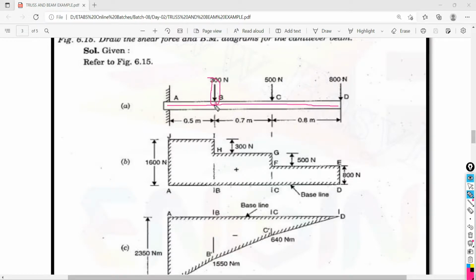That's why we took this beam like this, then took one other beam in continuity, then another beam in continuity, coming to the end. So actually the beam is single, but we modeled it in 3 parts so that you get the joint at this point. Got it?